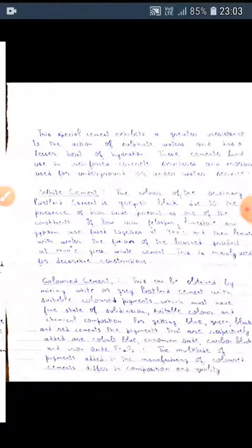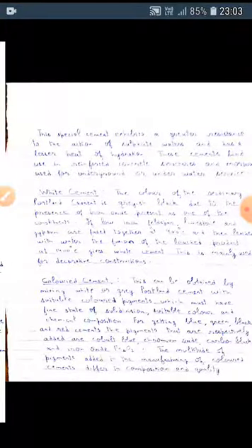In distinction to mineral pigments, for example chromium oxide, of which up to 7% is added into Portland cement, organic pigments are used in small amounts from 0.05% to 0.2% of the mass of Portland cement. Colored cements are classed as hydraulic binder since the main constituent is Portland cement.